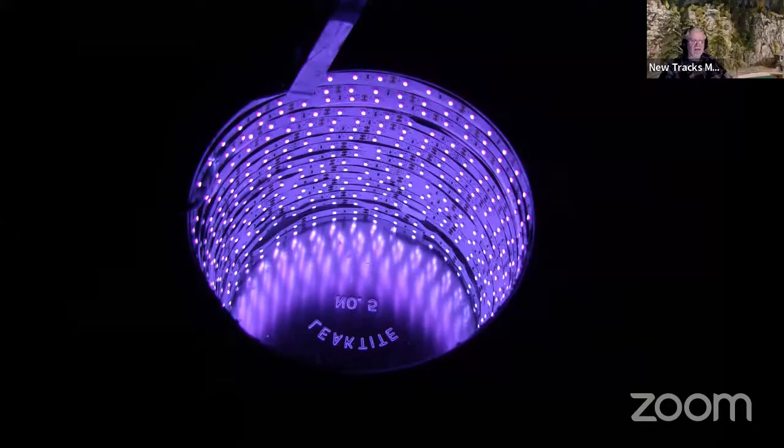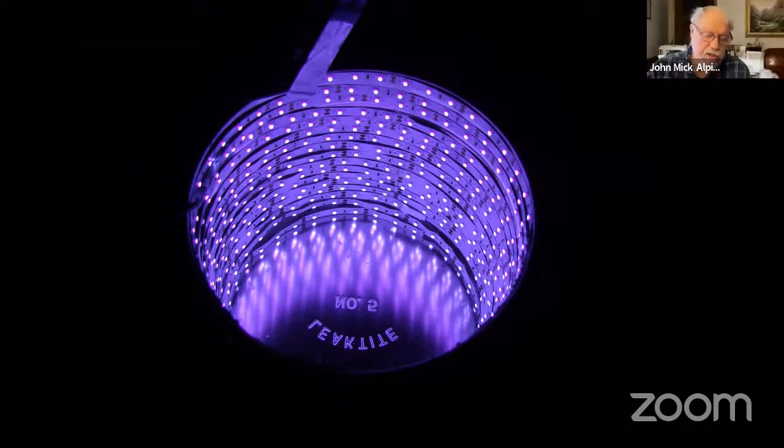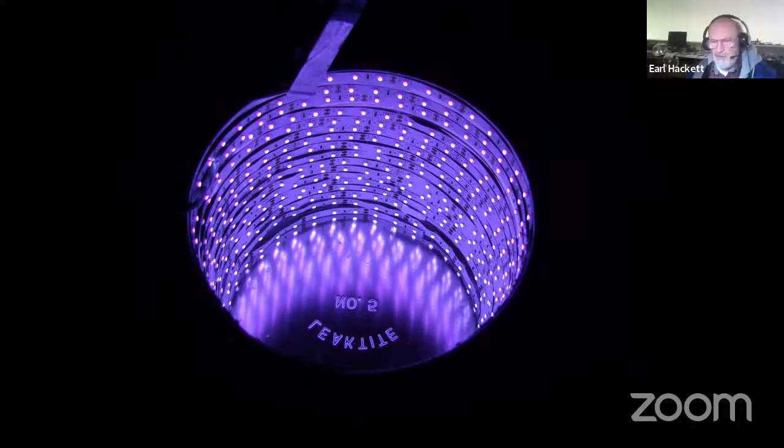Wow. So when you put something in there, it's pretty intense light. I put a lid on it when I'm actually curing stuff, because there's a lot of light in there, and it really warms the thing up. Can you over cure it? I leave it in for about 2 minutes. That's about all it takes. Sometimes I'll leave it in for 3 if it's a real complicated part. But I have run some stress strain tests on them, and 2 minutes seems to be about the right number.